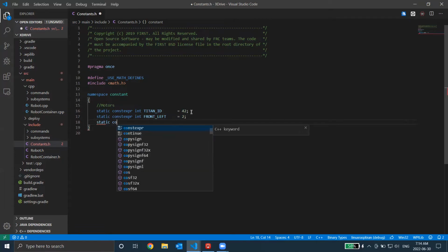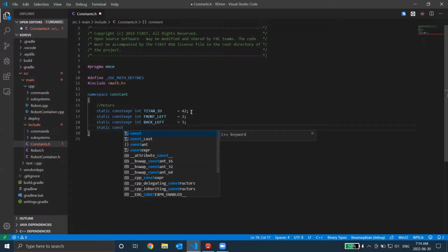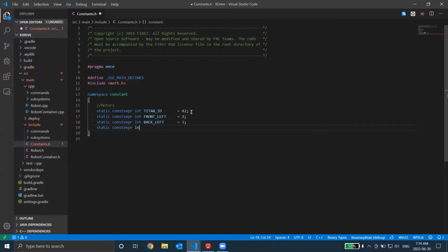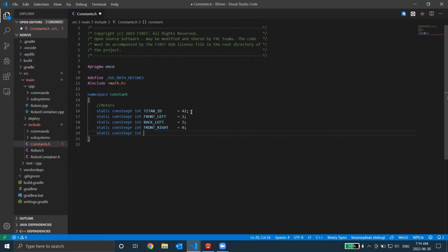If you remember when we built the robot yesterday and we mounted the motors, I talked about getting a little sticker and labeling your motors. So setting the direction that is going to be front for the robot, and then deciding which motor is which on which port. So 0, 1, 2, 3. Now you're just defining that port number for each motor. So the front left is on motor port number 2.